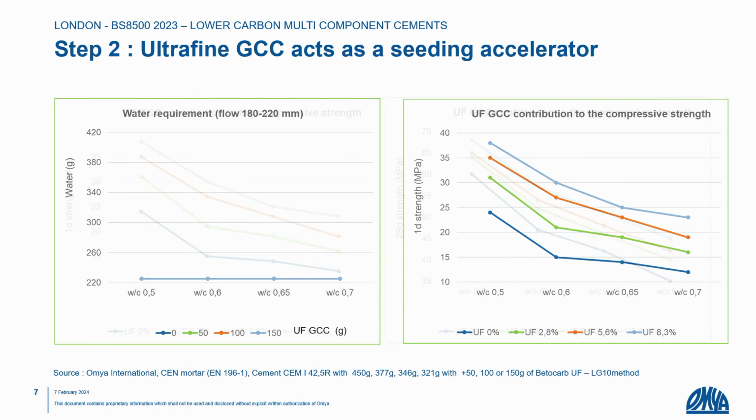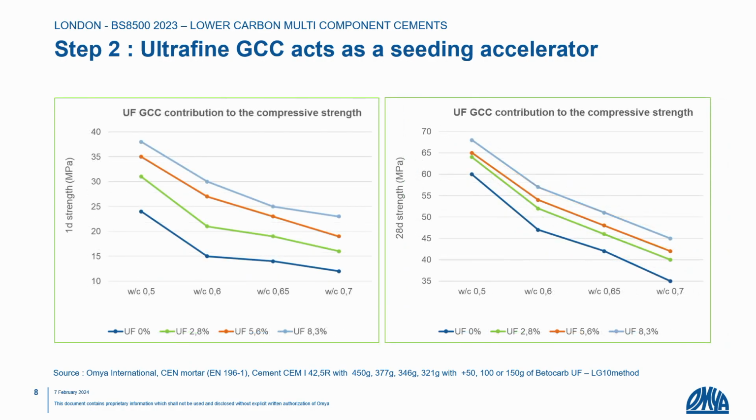The next step here is this information at 1 and 28 days. If we want to evaluate and to feel and to measure, because the question is to evaluate, to have some data, the influence of the water concentration or water to cement ratio, the edge, and also the concentration of this ultrafine calcium carbonate, we can, for example, compare the strengths at 1 day and 28 days.